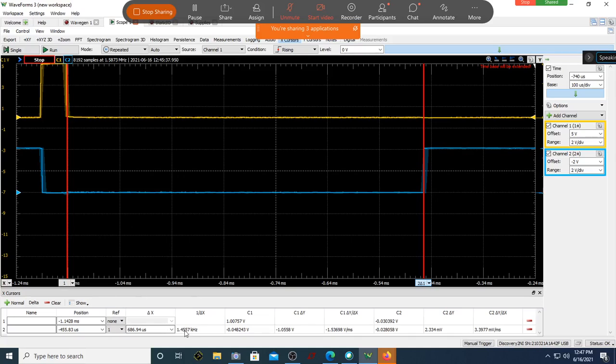Let us see whether it is 68 microsecond or 680 microsecond. Can you see now the conversion time is 686 microsecond? Does the conversion time depend on the frequency? Yes, it depends on it. So for a 100 kilohertz clock frequency, the conversion time is 686 microsecond.